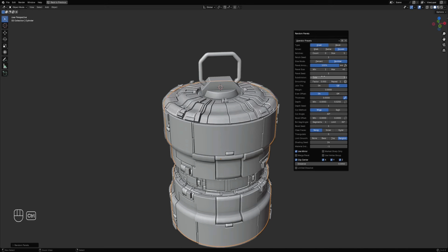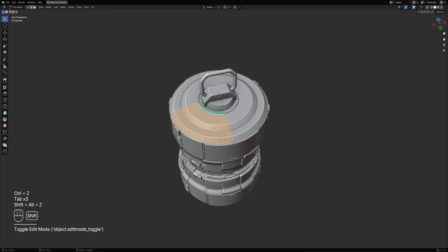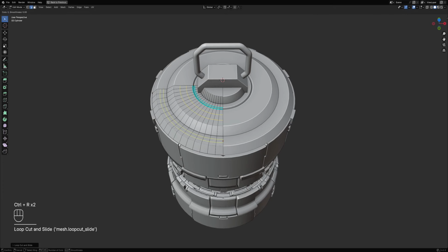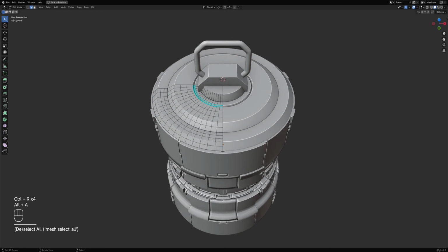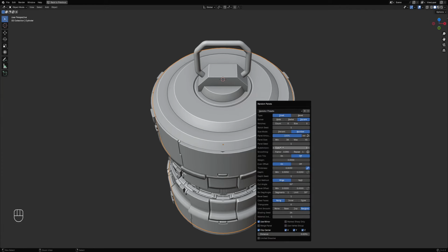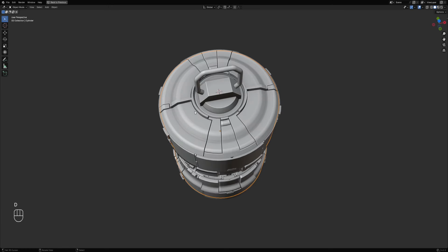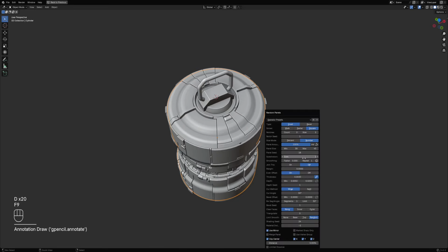Okay, so flip the center to get rid of the symmetry line, and that weird line in the center. So we need to add more edge loops to this because there's not enough detail there to actually. Oh, by the way, the selection also works in edit mode, but I might remove it in edit mode. There we go. So it has more tendency to create lines this way because we added more topology on that direction.